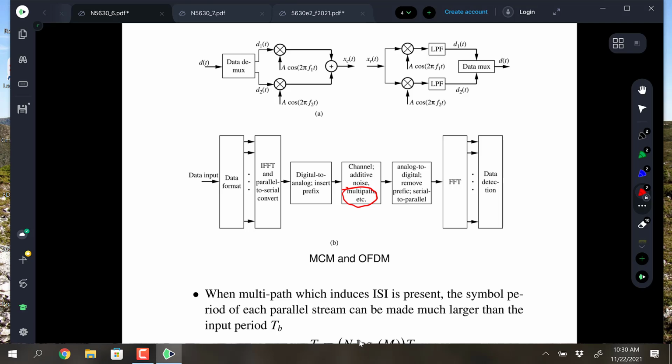I guess the obvious question is, what's the advantage of this over... Okay, I'm glad you asked, because I've got the answer to that. This is a very cool modulation scheme. The first thing is, why would you do it? You're thinking, oh, I have to have an IFFT at the transmitter and an FFT at the receiver. Isn't that going to be a showstopper? Well, it's efficient. Multi-carrier modulation was not necessarily purely orthogonal, but the idea of OFDM with the IFFT and FFT was being efficient, right? Because we know we can make that efficient.